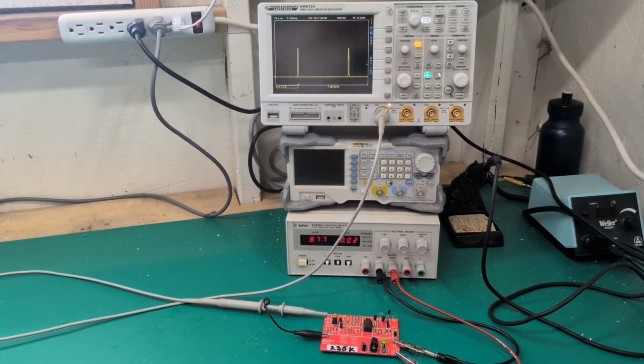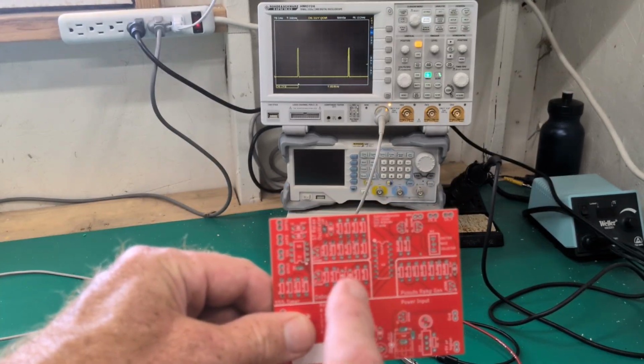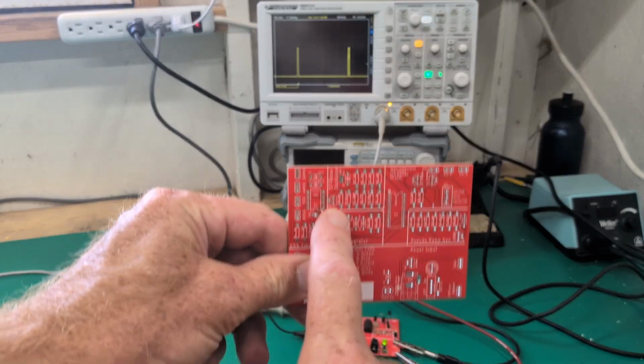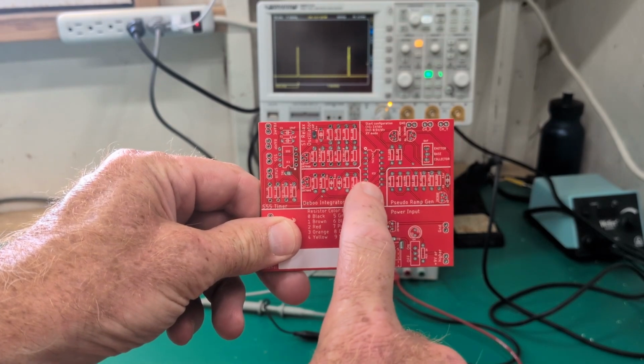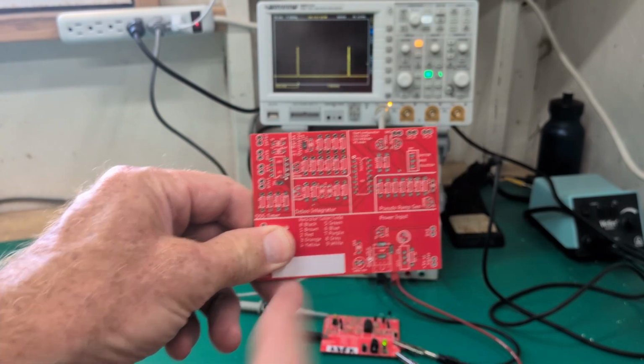If you've been asking yourself, why don't we just use a 555 timer, you're correct in theory that this would work, but in practice I wanted you to learn some new concepts this week, so we're using a different oscillator. Assembly-wise, you'll be assembling the circuit in this upper corner here as well as the socket for the TLC-274.